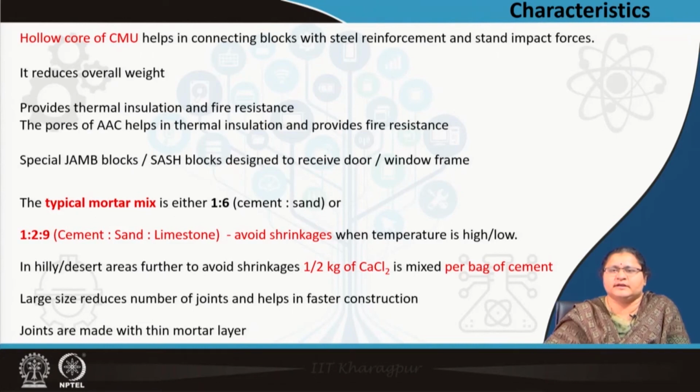As I told, it is not completely dry. Yes, it has an application of mortar similar to that of brick, and the mix is 1:6, which is the cement to sand ratio of the mortar, and the joints are very thin.